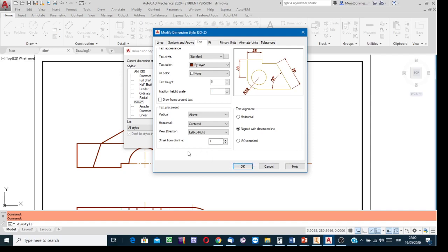Why? Whenever the dimension of the feature is wrong at the drawing stage, the drafter made a mistake and the distance from here to there is the wrong value. Instead of trying to change the drawing, just change the dimension. But although the projection is wrong in size, if you change the dimension manually, then that replaced dimension, the new value, must be underlined.